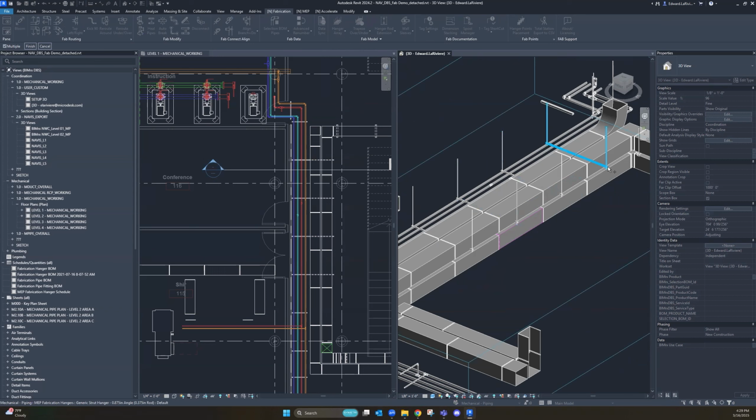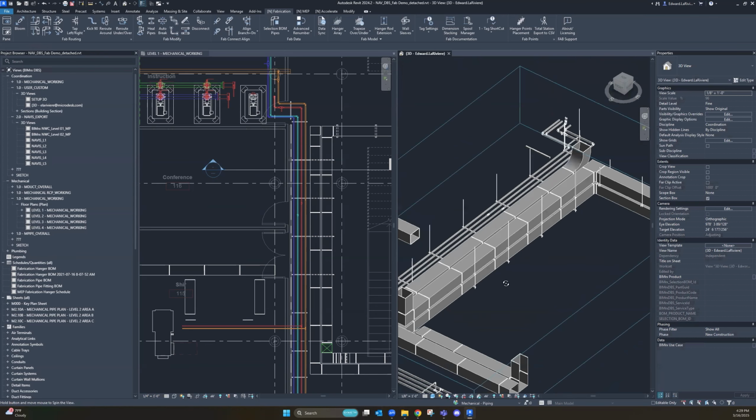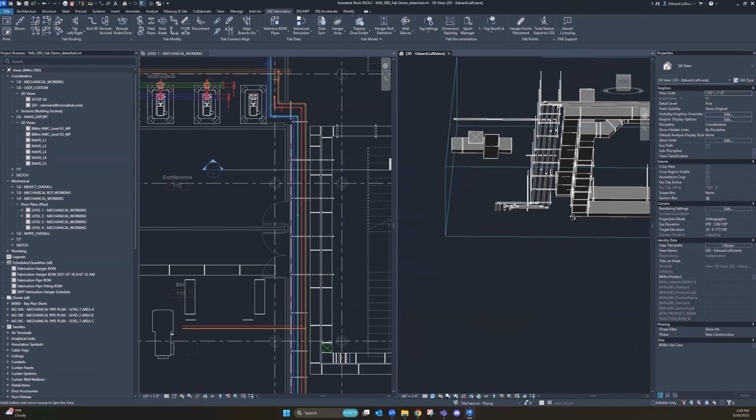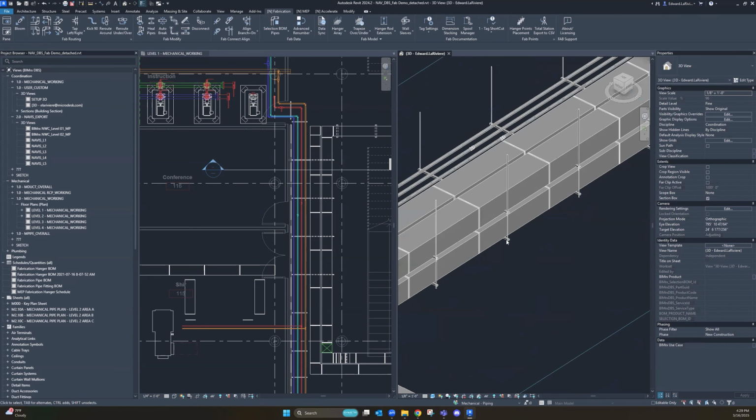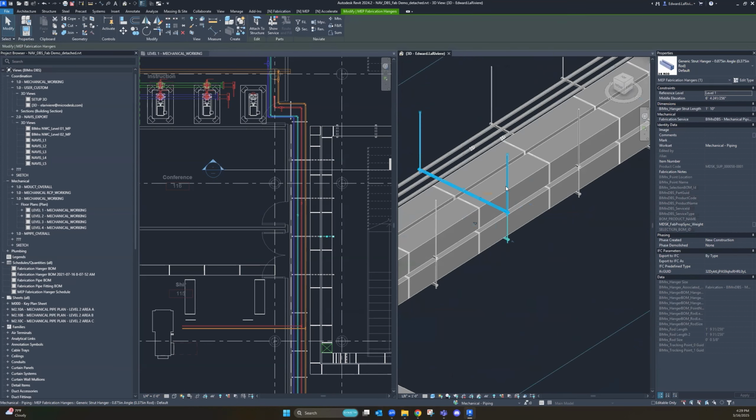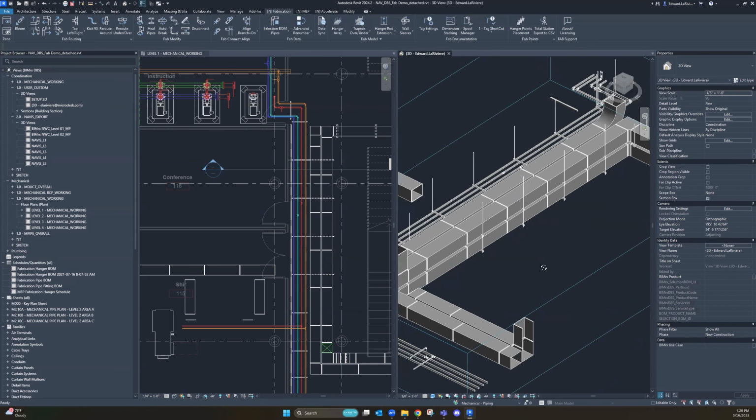We'll see next it's asking me to choose the hangers I would like to work with. So I'm going to choose this whole rack here so that all of these can be copied down to support the below. As I click Finish, we'll find it generates another rack right below that top rack, but only including the elements I've chosen. If we click on any of those runs, we'll see that those rods terminate at the height of the hanger above.